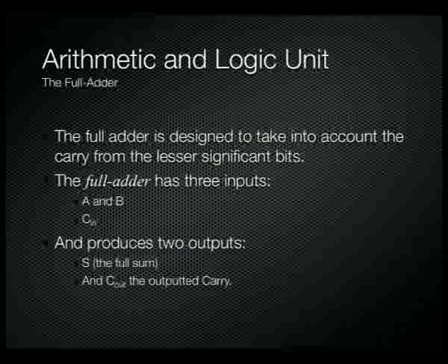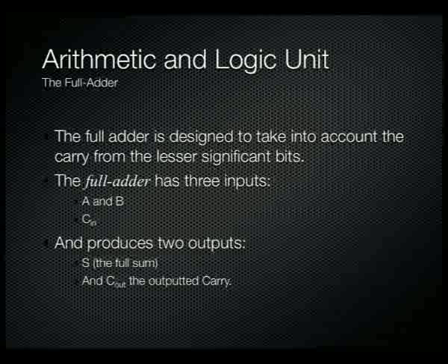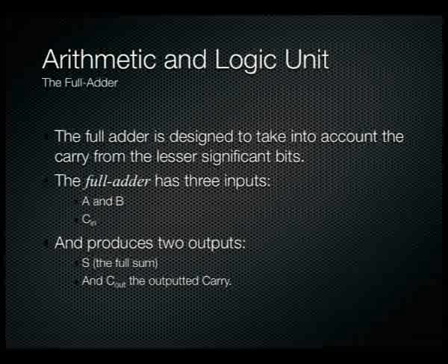Of course, it's not very useful if you want to add multi-bits together. Then of course you've got to take into account the carry bits. So the full adder is in fact designed to take into account that carry bit from the lesser significant bits. So the full adder has 3 inputs, A and B, like the half adder, but it also has a third input, which is the carry in.